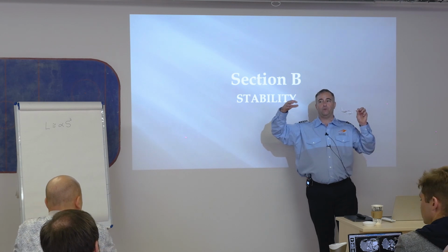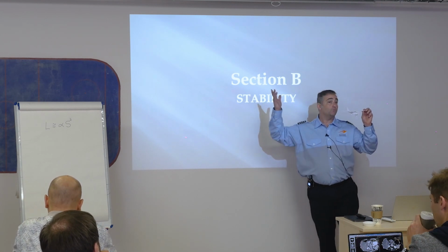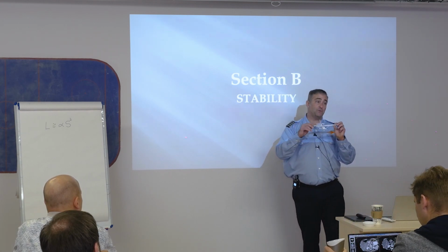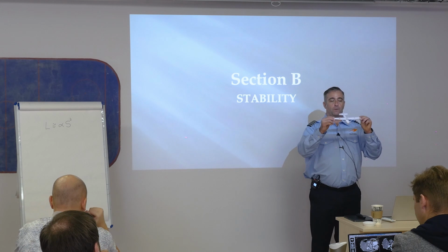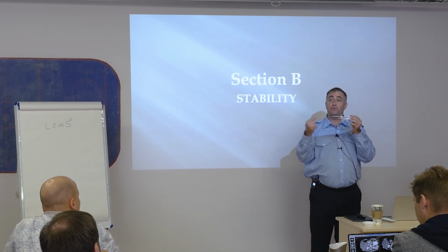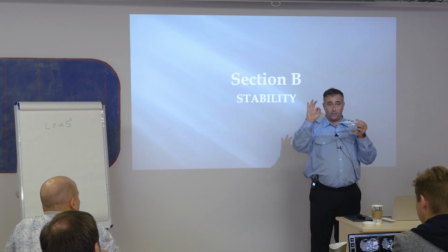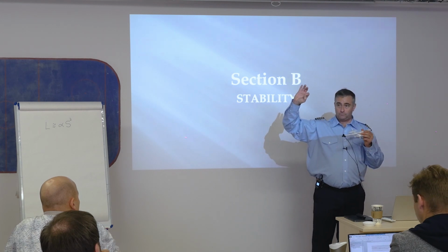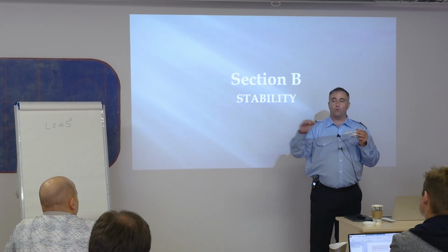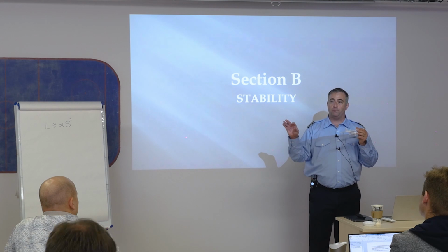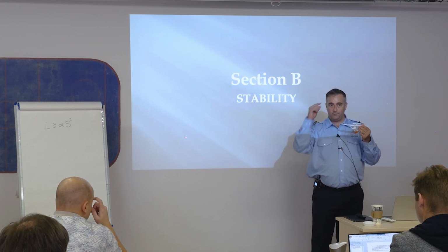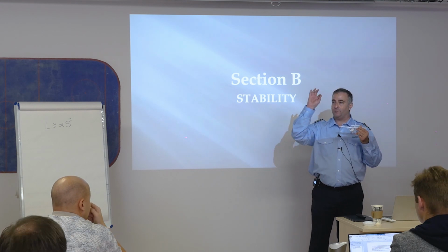Like I mentioned yesterday, we're not going to talk too much about stabilator because you just won't use one in the private pilot course. Not unless you're flying a Piper airplane, and most people are using Cessnas. So the elevator makes me go up and down. Now, something interesting is that all three of these axes join at one point. That center point is called the center of gravity. So all motion around this airplane goes through the center of gravity. Kind of planting a seed there in everyone's head.